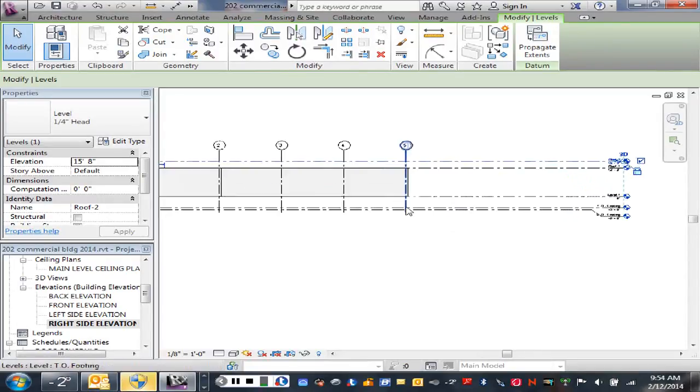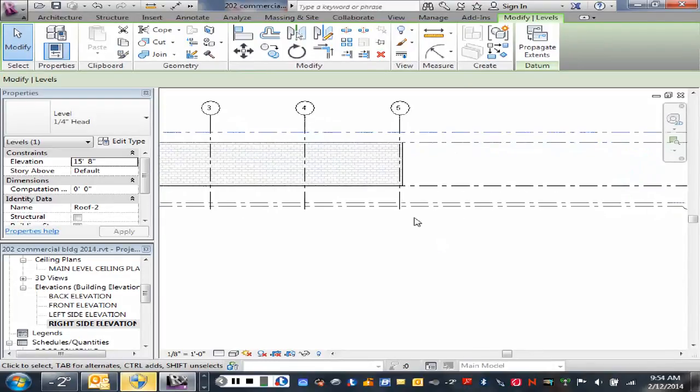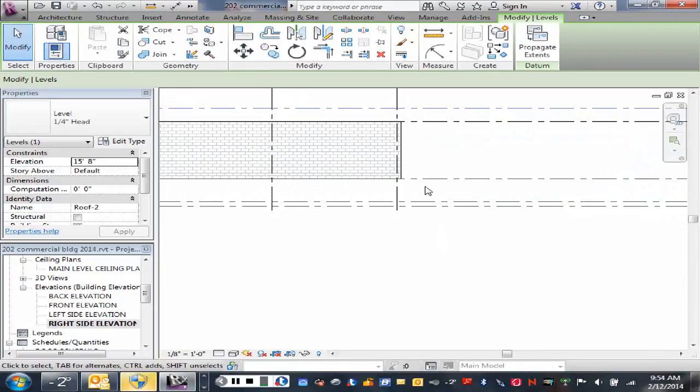Okay, let's go down then from this level down. We talked about putting a basement in this building. And if we put a basement in this building, it's commercial construction, so one option would be, again, to go with bar joists and beams and put a metal deck on that and then pour a concrete floor on top of that. That's one option. The other option is to go with precast concrete planks. You all familiar with precast concrete planks? Probably talked about that in your methods and materials class a little bit. Okay, so we're going to opt for that.